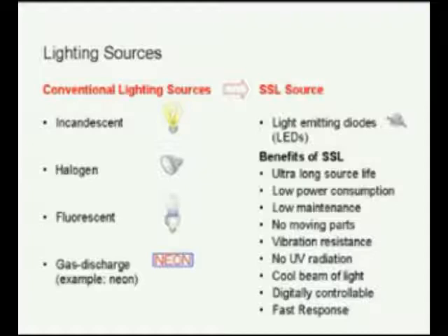Finally, and one of many other attributes for LEDs, they have very, very fast response. There are certain types of LEDs, infrared LEDs in fact, that are used for communication. Your television remote, for example, most likely has an infrared LED that is turned on and off very quickly in order to communicate with your stereo or entertainment center or television. As a result, LEDs can turn on and off very quickly and don't have the typical thermal lag associated with incandescent and halogen sources. You can often see this effect if you look at the brake lights of cars that